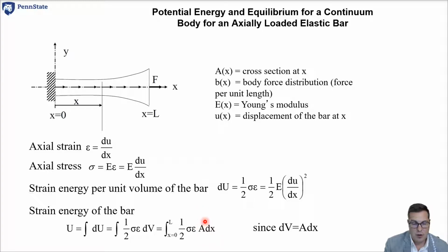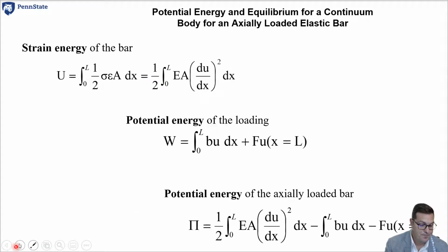This is important in our development of, really what we're after is a development of a truss element in finite elements. So trusses can have different thicknesses, and we just bring in different widths or cross-sectional areas, and we bring it into this area term. So that can be a little confusing. We're working in 1D, but we also have an area term, cross-section, associated with the continuum body we're looking at. So our strain energy is there.